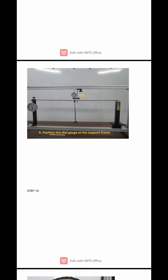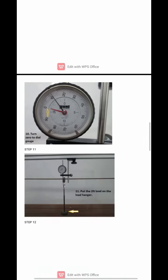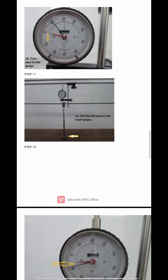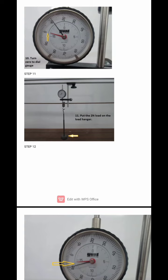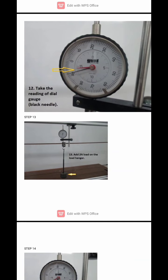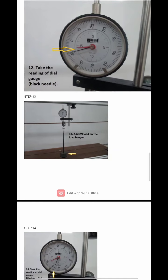Position the dial gauge at the support frame. Turn the dial gauge to 0. Put the 2 Newton load on the load hanger. Take the reading of the dial gauge black needle.